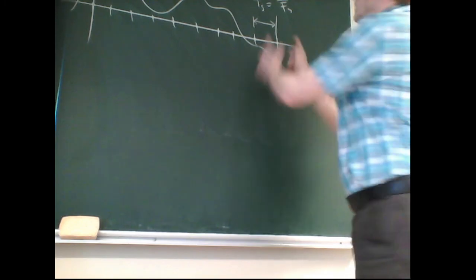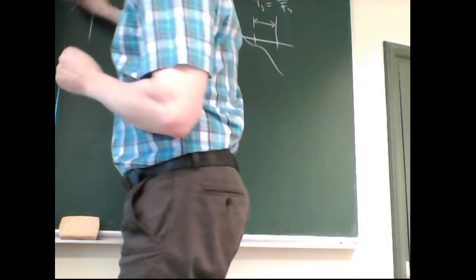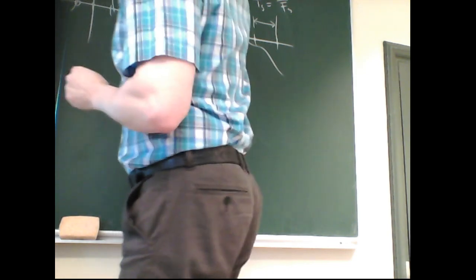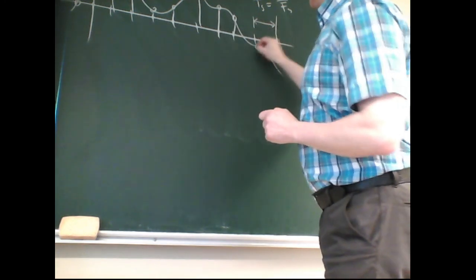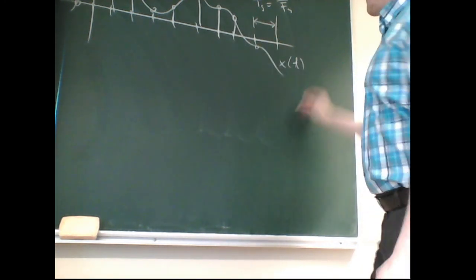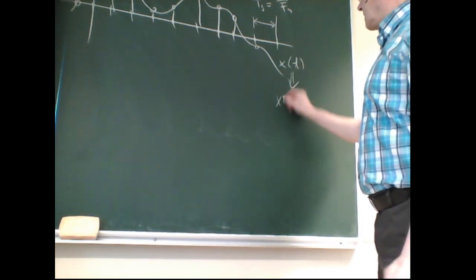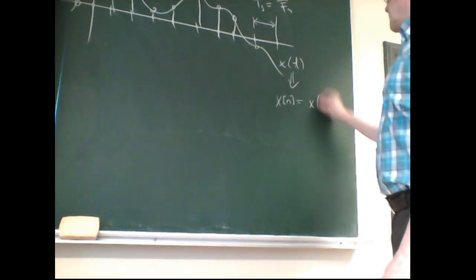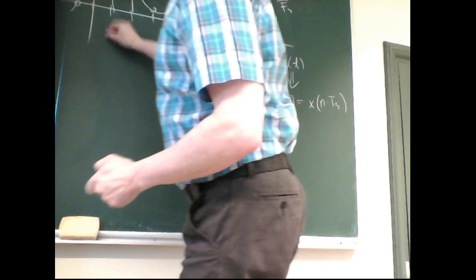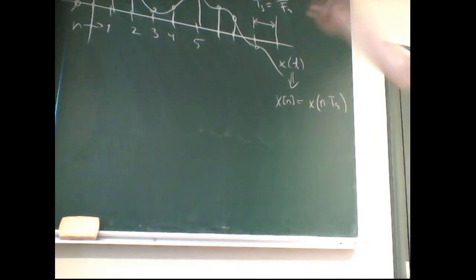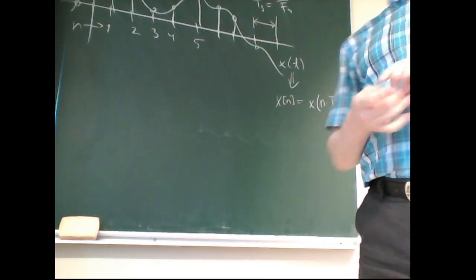So it's the time difference between two samples, and then you basically just take the snapshot of the signal at those times. Quite simple. So if you have x of t, then that becomes x of n, simply x at time n times Ts, where this n is just the sampling index. Okay. So sampled data is nice, since then you can put it on a table on a computer.